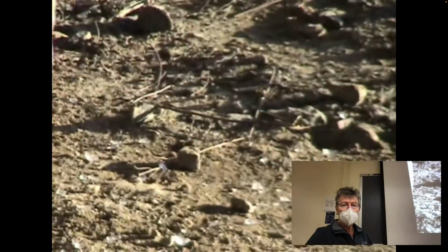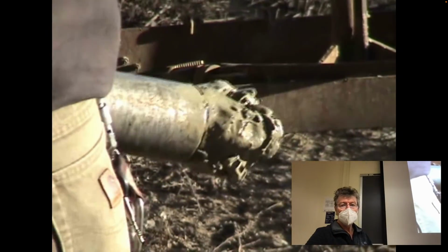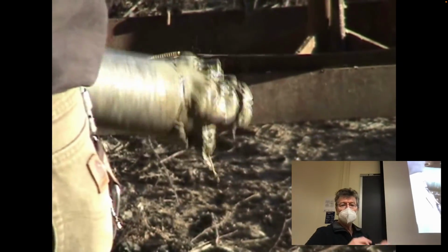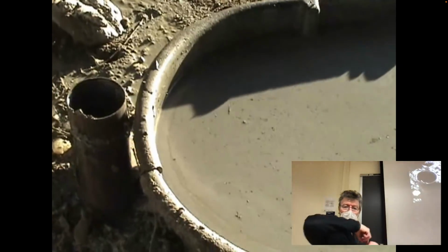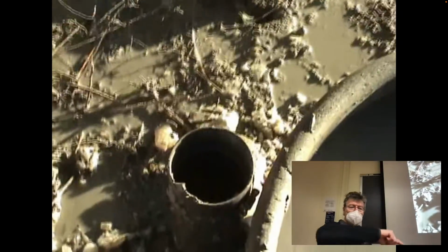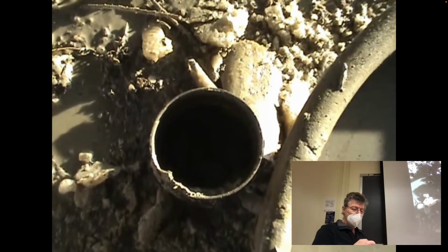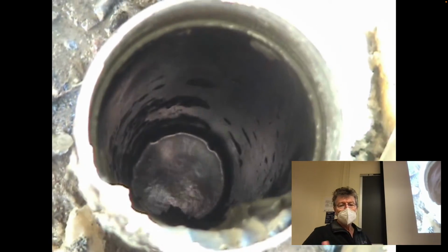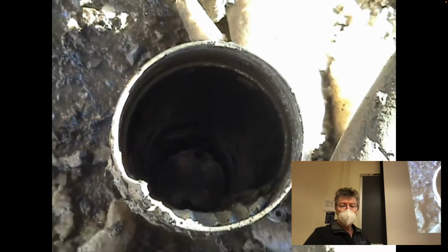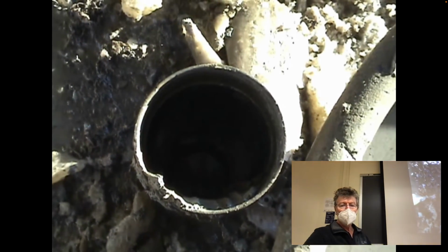So this is the bit that's been retrieved. It's been connected to the drill rig by drill string, which is all these look like 5-foot lengths of steel. So these are these 3 tricones. They're not motorized, but they're on spindles. And when you push it on the bottom of the hole, it just runs over it like a car wheel. And the individual pieces, which are stress concentrations on the tricone bits, allow it to break off pieces. And those pieces are washed back up the hole with the return fluid to the surface.